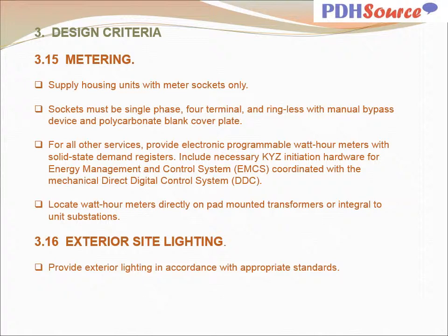For all other services, provide electronic programmable watt-hour meters with solid-state demand registers, including necessary KYZ initiation hardware for energy management and control systems, EMCS, and coordinated with the mechanical direct digital control system, DDC. Locate watt-hour meters directly on pad-mounted transformers or integral to unit substations.